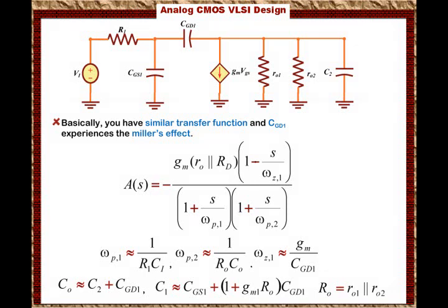So far, this was a very important circuit we have discussed. We said that what's the frequency response of the common source amplifier, and we used nodal analysis to derive the transfer function. When we use the nodal analysis, we come up with two equations, and then we eliminated one of the unknowns because we have two equations. We used one equation to eliminate one of the unknowns, and then we end up with expressing V out in terms of VI, and we came up with the gain equation. We end up realizing that there is a 0 located in the right half plane and 2 poles, and the location of the 2 poles are very close to the Miller theorem that we have obtained.